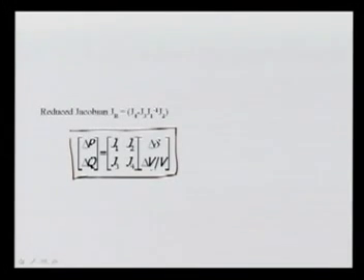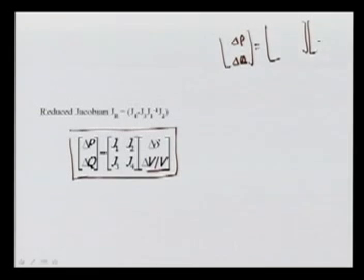Now, the question again arises: why are we using del V by V, why not V? You know, the mismatch vectors for power are the change in real power and change in reactive power. We go for the Jacobian matrix, and here we go for the change in the state vector, that is delta, and change in V.